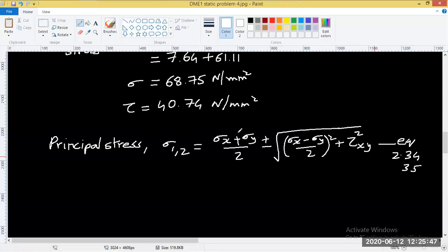Okay. So here you see what all you know. You know two types of stresses. So you know sigma x, that is a combined stress, and this is tau xy. So what we'll do, we'll just equate this for sigma x. So sigma y we'll just eliminate. You don't need to learn by heart many formulae here. Most of it is available in the data handbook. So we'll just remove this, make it 0, because we are considering the combined stress case.